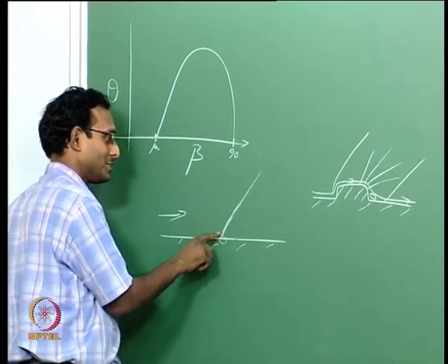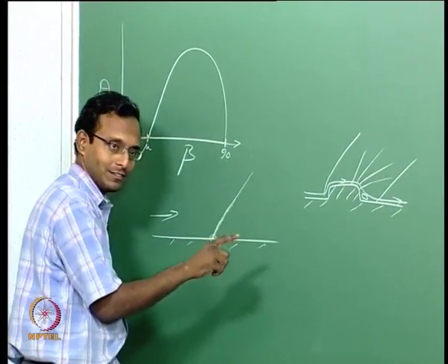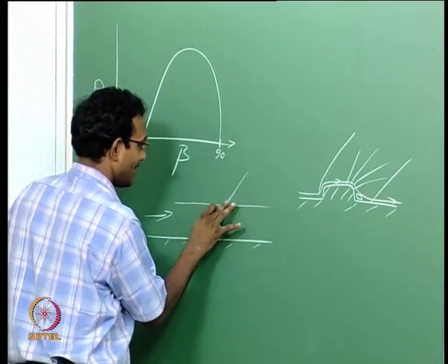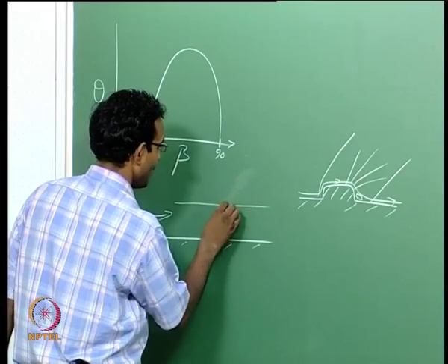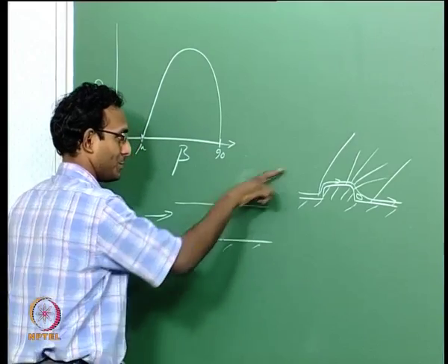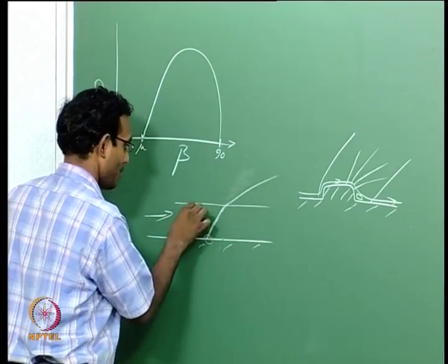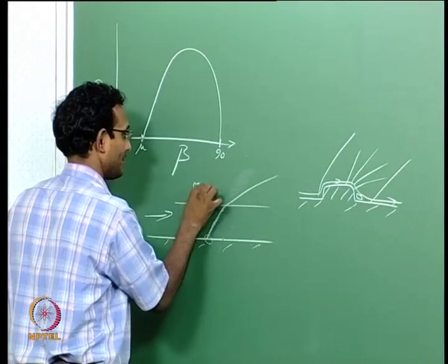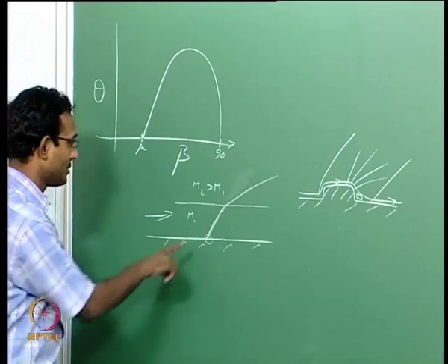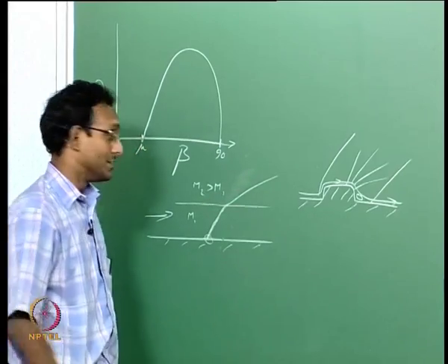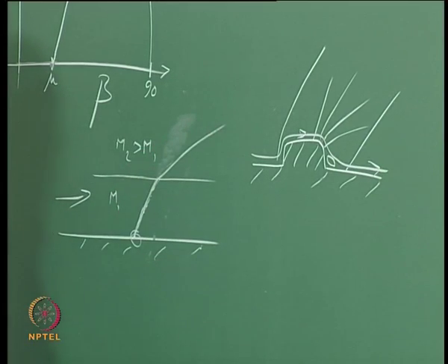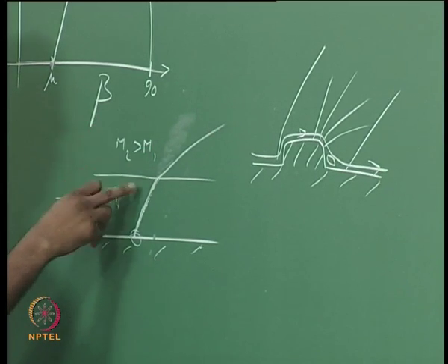and this disturbance is still travelling into this whole flow field. If my Mach number changes, say above this line, then it will be carried by that fluid with that new angle. This is a disturbance, it is carried through by this. Say above this line my Mach number is higher, and this is M1. If I had such a situation, it is just going to do something like this. This disturbance is propagating from here, but it is carried through by here. This is what I will see. How will I arbitrarily have different Mach numbers?